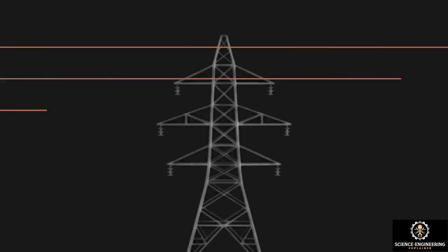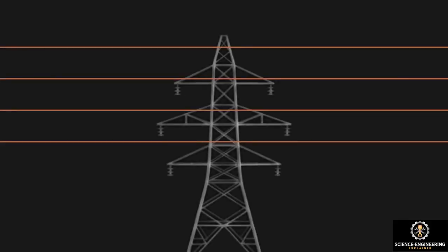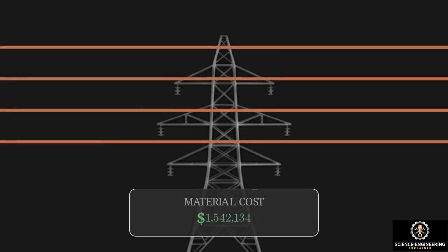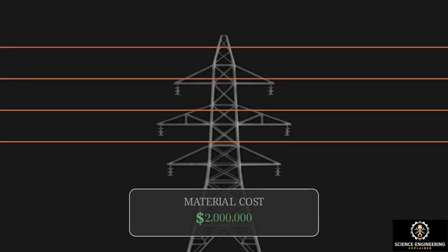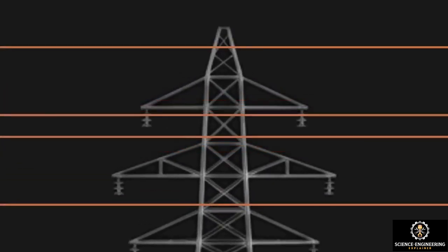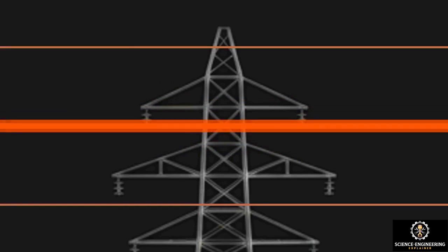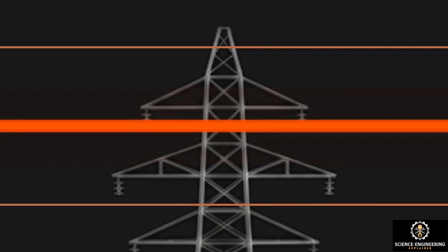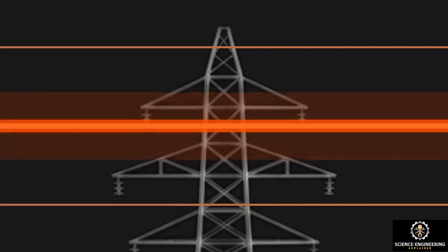However, this solution introduces an economic bottleneck. Doubling the power phases in this configuration requires 4 individual wires, which doubles the material cost of the transmission line. Combining the 2 neutral return wires to save material creates a thermal hazard. Because the currents are out of sync, the shared wire must carry a higher combined load than the supply lines.